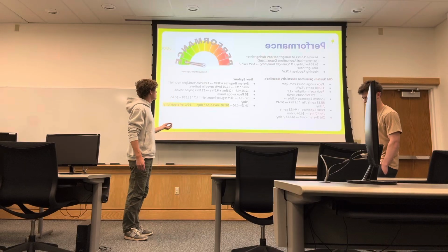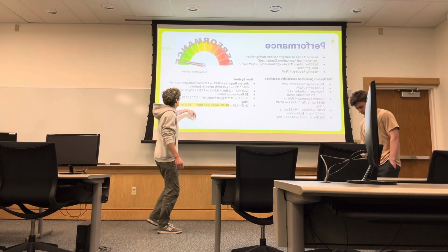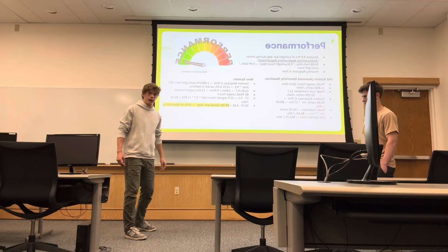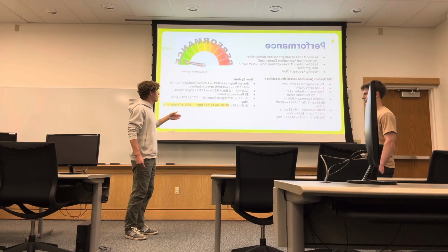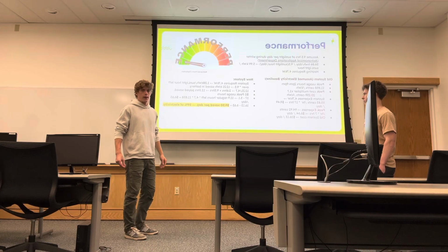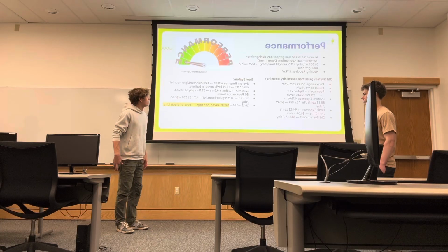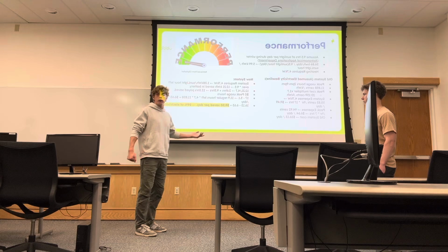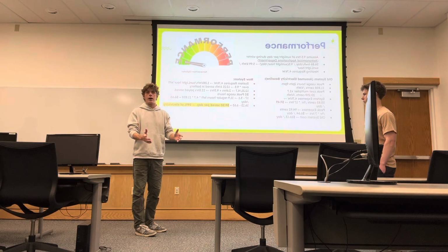So we take that small excess energy, which is 1.28 kilowatt hours of sunlight, and multiply that by the 9.5 hours that the sun is out during the day, which gives us right about 12.21 kilowatt hours that's going into the battery.